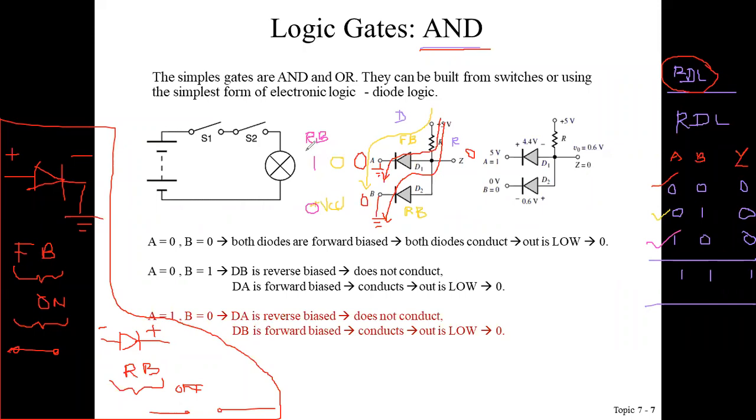Yes, diode one is definitely reverse bias because cathode is connected to plus VCC, anode is also plus VCC. According to the voltage level, we can determine. But anyhow, here it is 1, it is reverse bias. This is forward bias condition. So under this condition, this plus VCC is directly connected to ground through this path. So all the charges available here are directly connected to ground.